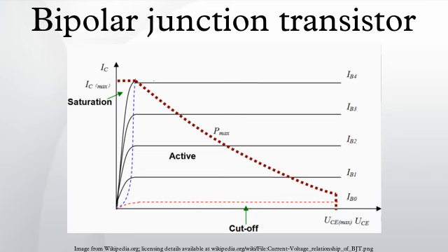This gain is usually 100 or more, but robust circuit designs do not depend on the exact value. The value of this gain for DC signals is referred to as hFE, and the value of this gain for AC signals is referred to as hfe. However, when there is no particular frequency range of interest, the symbol beta is used.